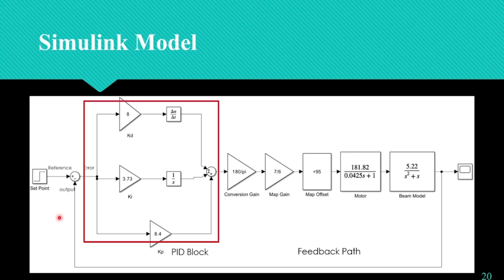Hello, my name is Aditya Dipro, ID 2006018, and I am starting my part of the presentation now. Here we can see the Simulink model of our whole system. At first, we are setting a reference point, which is our final position of the car that is fixed from our first sonar sensor. Then we are taking current position of the car as feedback from second sonar sensor. Then we calculate the difference of the reference and current position of the car and calculate the error signal.